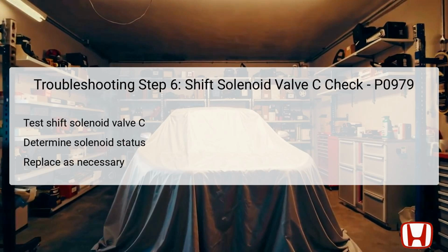In the 6th step, you will focus on a final assessment of shift solenoid valve C. Conduct a thorough test of the solenoid valve to confirm its operational status. Should you find that shift solenoid valve C operates correctly, this indicates that it's functioning as intended, and thus, the next immediate step will involve replacing the shift solenoid wire harness to eliminate any potential wiring issues before verification.